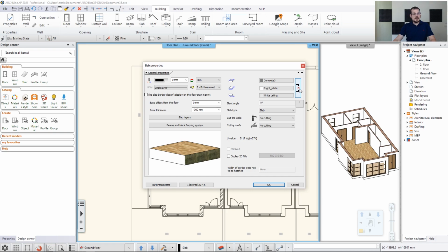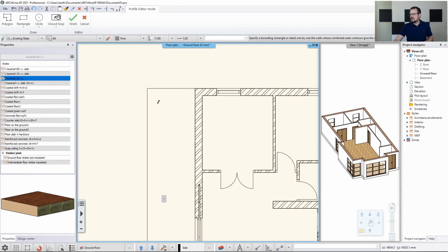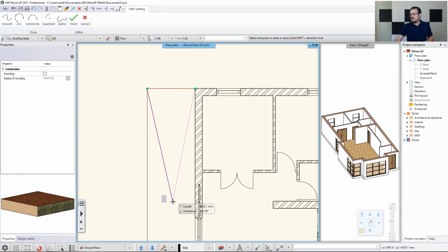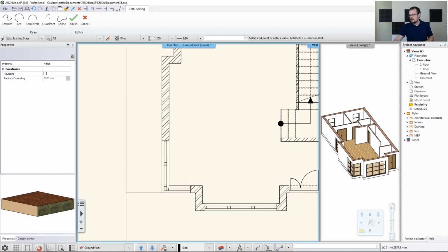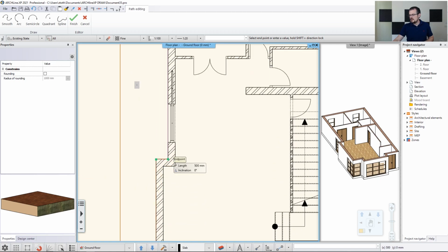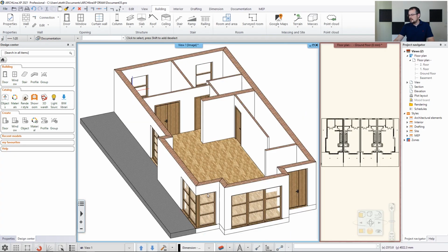And if I hit this tab, then all the sides, even the sides and the underside, are going to be concrete. So I don't have to change them manually. I just link them up together. All right, so let's hit OK. And now I go to Slab. I go with Slab in sketch mode, and I'm going to track the lines over here. If I do it correctly, let's click on the nodes, and I hit enter to finish my command. I have a very nice slab on the outside, like so.